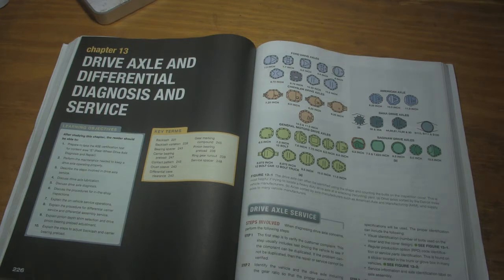So when we have a vehicle in the shop, we want to check the vehicle history if possible, and we also want to look up TSBs. Part of identifying the customer's concern is going to be going to the computer and looking up service history and technical service bulletins. And so manufacturers tend to have common trends with certain components failing, and you may have an